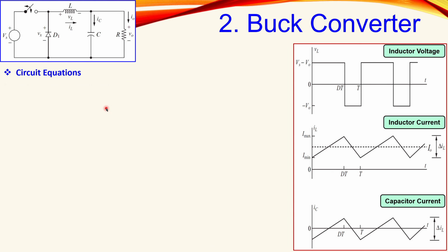Okay, now let's also look at the circuit equation for the load current at steady state. We can say, since it is steady state, that means there are no variations anymore, the capacitor will behave as an open circuit. So the inductor current will be exactly the same as the load current at DC, or on average.